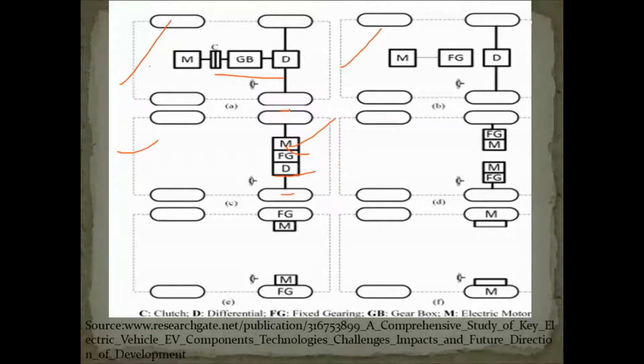Chevrolet Spark and Nissan Leaf are examples of this type. We will further be looking at this ahead. In figures D and E, the differential action is being obtained by two separate motors for the two wheels at different positions, as you can see. And in figure F, motors are placed inside the wheel to produce the in-wheel drive, and a planetary gear system is employed here. So it uses the advantages of a high speed ratio and totally removes the mechanical interaction by removing the gearbox.